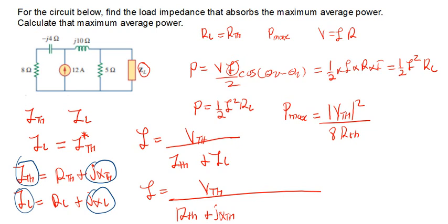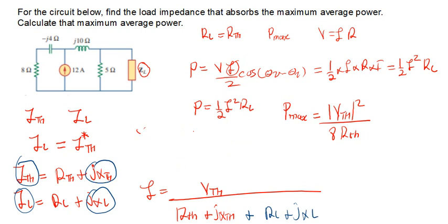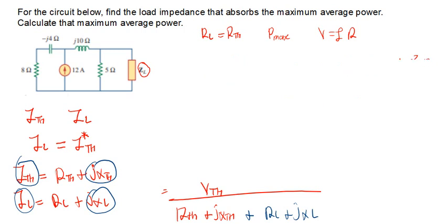And how do we get that maximum average power transfer? We get it from the current. If you have maximum current, you're going to have maximum average power transfer. So remember that at this part you're also adding your load resistor plus the reactance of the circuit there. Let me erase this part. We'll bring this back if we need it.